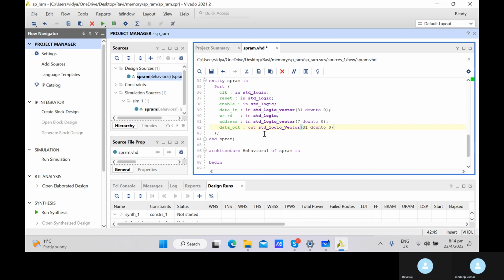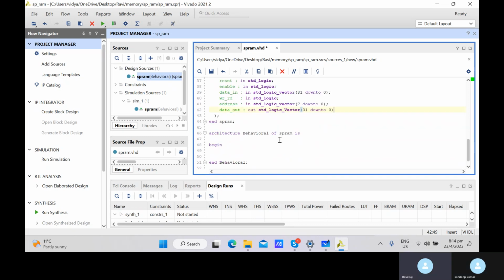In that case, you must understand single port memory, because single port memory is smaller than dual port memory in size. So once you are writing the code for ASIC, most of the time you will be using single port memory, and that's where you should understand how to interface the SPRAM in the ASIC. But on the FPGA, a dual port memory will always be available.